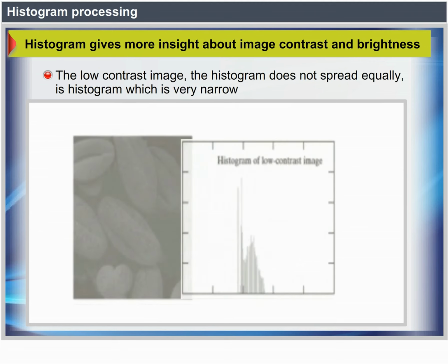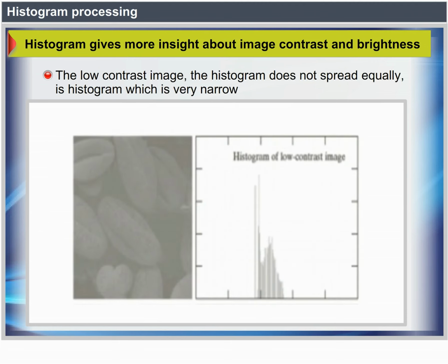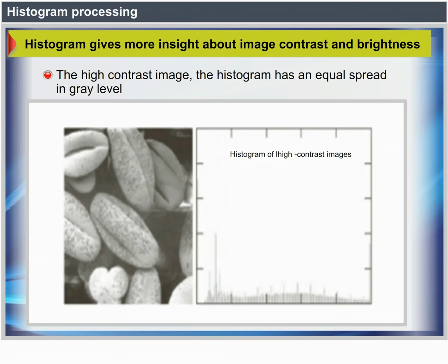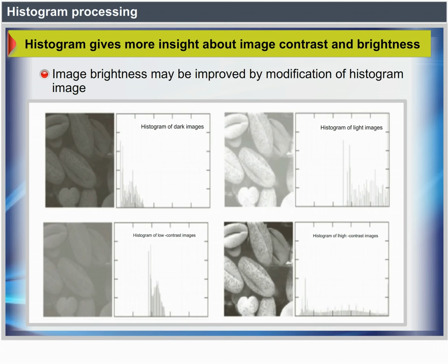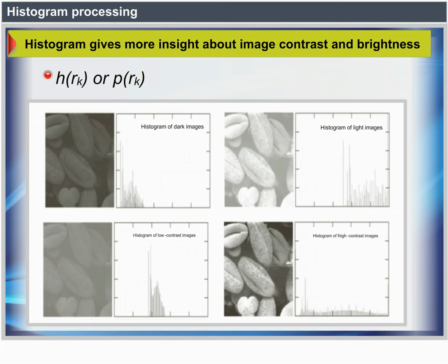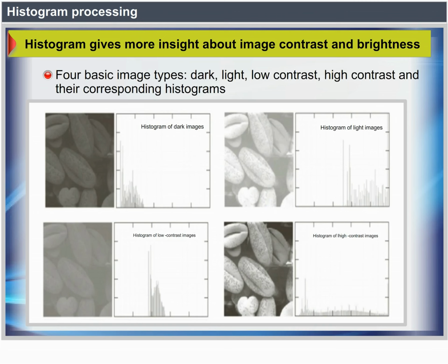Histogram equalization. It is the process that attempts to spread out the gray levels in an image, so that they are evenly distributed across their range. It reassigns the brightness value of an image based on an image histogram. It is a technique where the histogram of the image is as flat as possible. It gives more pleasing results across a wide range of images.